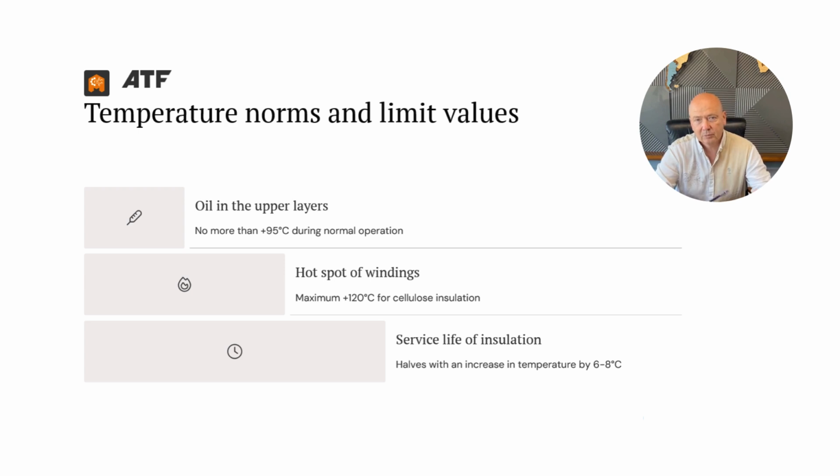Class A, from 105 to 110 degrees Celsius. Class B, up to 130, and Class H, up to 180. Exceeding these limits rapidly accelerates insulation aging. For example, every 6 to 8 degrees of temperature rise cuts the insulation's service life in half.